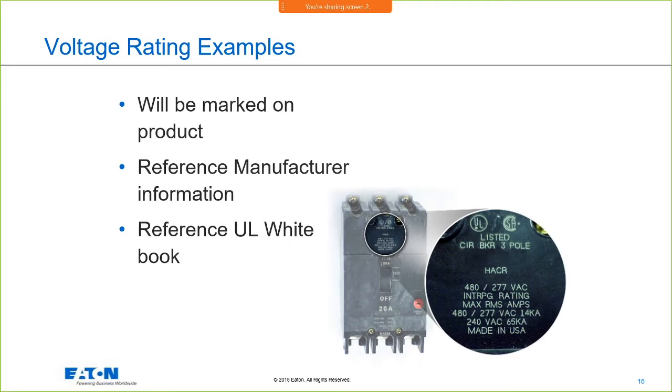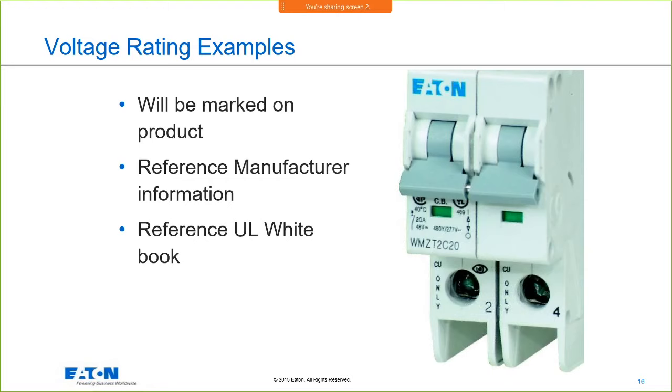Here is a slash rated breaker, 480/277. It has the interrupting ratings and all that information right there on the face, like David Williams loves. I know David Williams would love all the miniature breakers to have that information on the faceplate, visible through the dead front. And I'll explain these labels as well. I've got a good reference for you from UL.